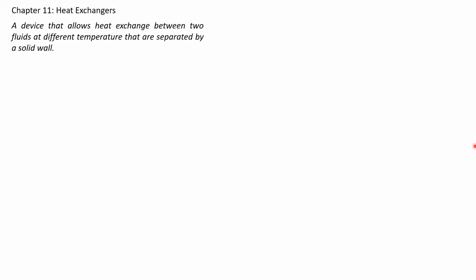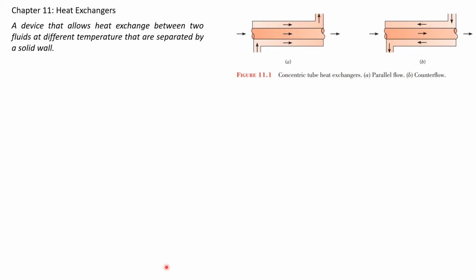In the radiator, there's a coolant that runs inside, and air flows across the tubes of the radiator, thereby exchanging heat. So that's one of the simplest practical examples of heat exchangers that we see on a day-to-day basis. Now, there are different types of heat exchangers, and based on applications and what type of cooling is favorable, we select what type of heat exchanger we need.